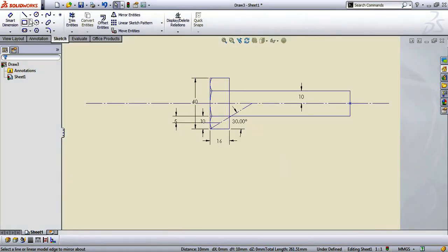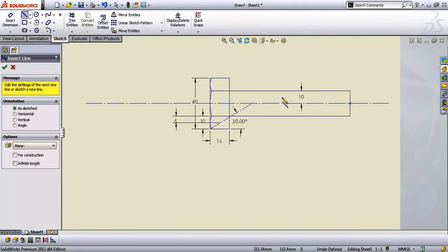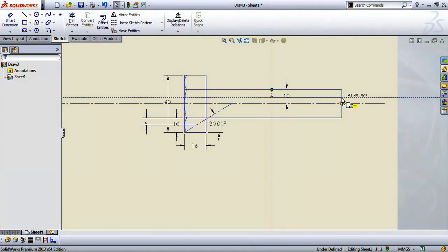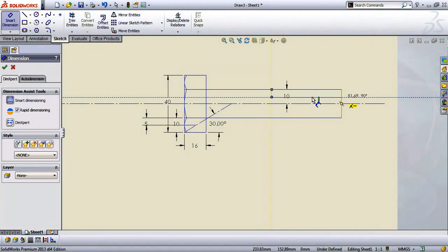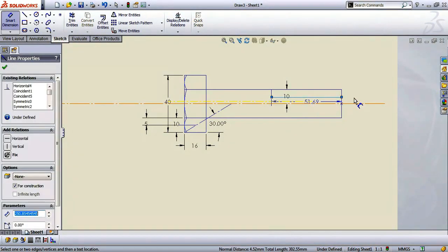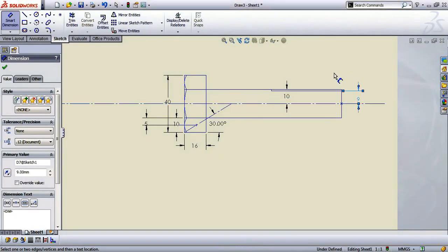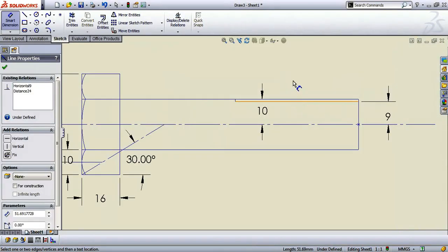Okay. Now we'll draw the nut portion. Okay, before that we'll draw the thread portion on this. Just take a straight line and connect it to this. Okay, usually thread diameter will be 0.9 times the diameter. So here I'm taking a radius. Okay, so it will be 9 mm, and the length of the thread is given how much, 50 mm.